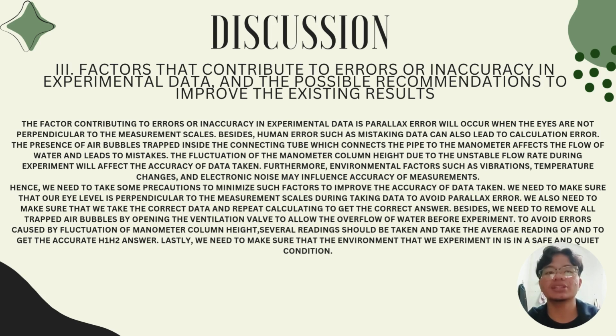Besides, human errors such as mistaking data can also lead to calculation error. The presence of trapped air bubbles leads to mistakes. The fluctuation of the manometer column head due to the unstable flow rate during the experiment will affect the accuracy of data taken. Furthermore, environmental factors such as vibration, temperature change, and electronic noise may influence the accuracy of measurement.